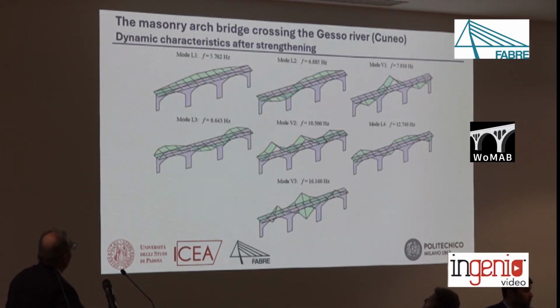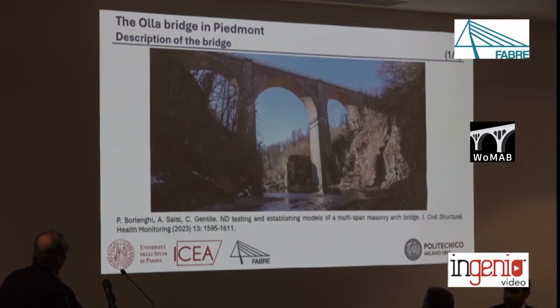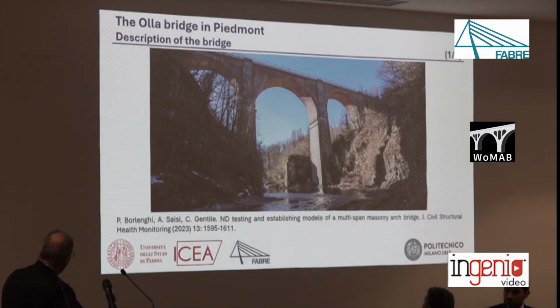Here we can see again the new mode shapes in the retrofitted condition of the bridge, and we can observe that the previous anomalies in the first two mode shapes have now disappeared, and also there is only one third lateral mode. Coming to the second bridge, most of the results obtained on this bridge have been already published in 2023.